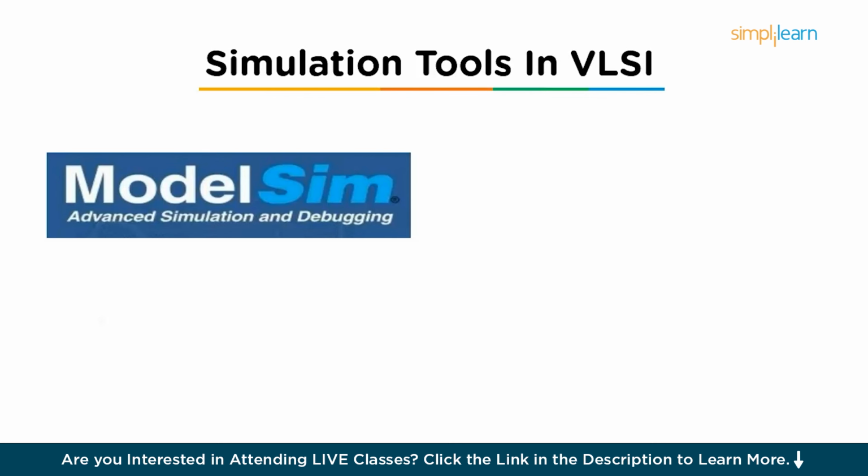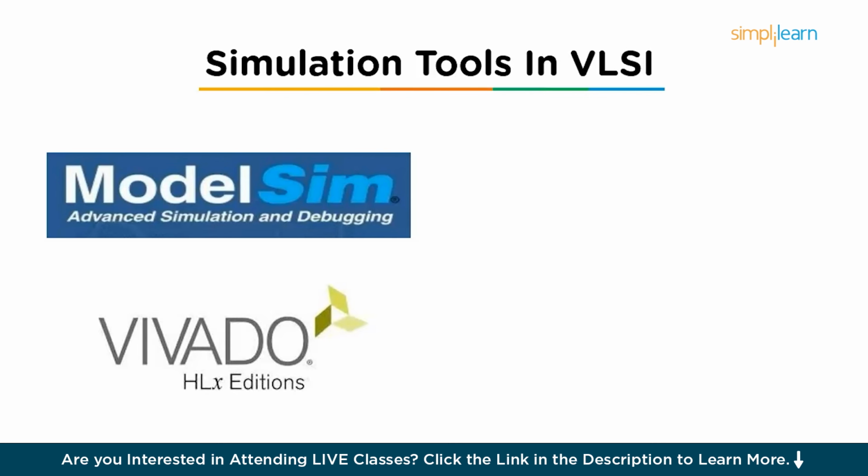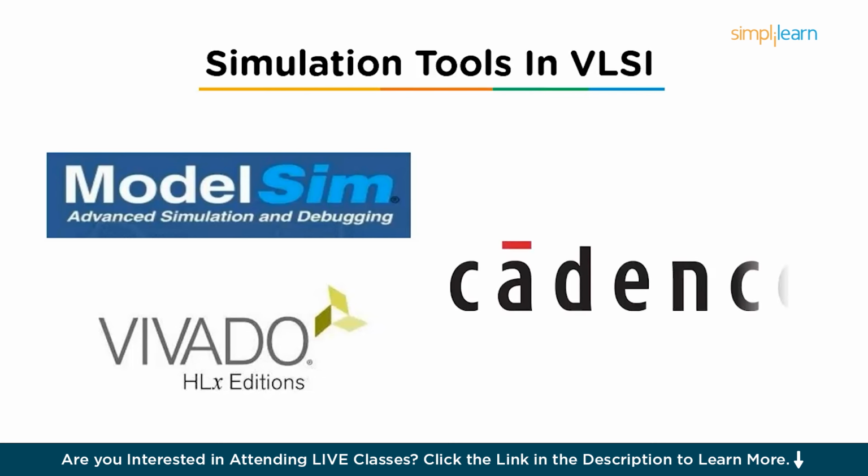Then the second is Vivado. Vivado is an integrated development environment, IDE, from Xilinx used for designing and testing FPGA-based systems. It includes simulation tools for both Verilog and VHDL designs and can be used to simulate both logic and timing. The third is Cadence. Cadence is another powerful simulation tool that supports both Verilog and VHDL. It is used for very large scale designs and can simulate everything from basic functional verification to complex system level validation.